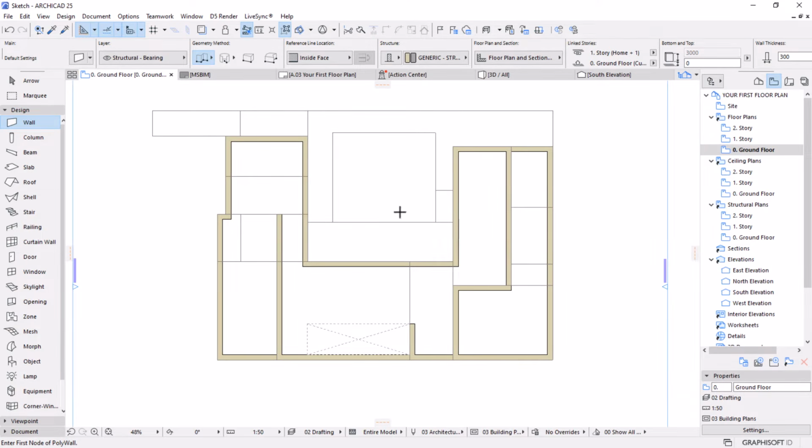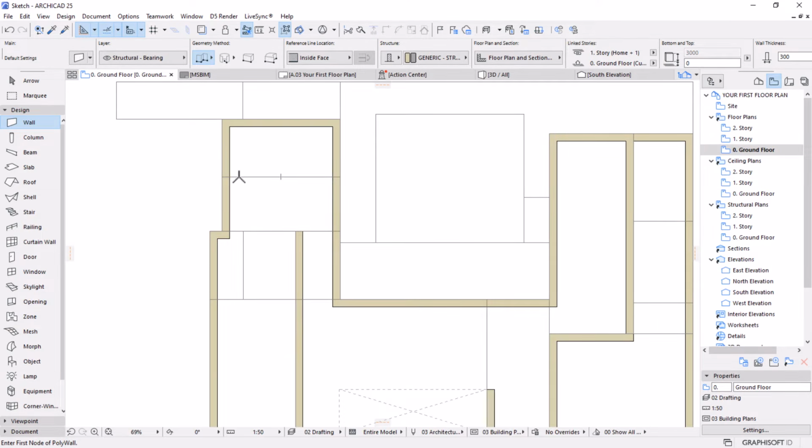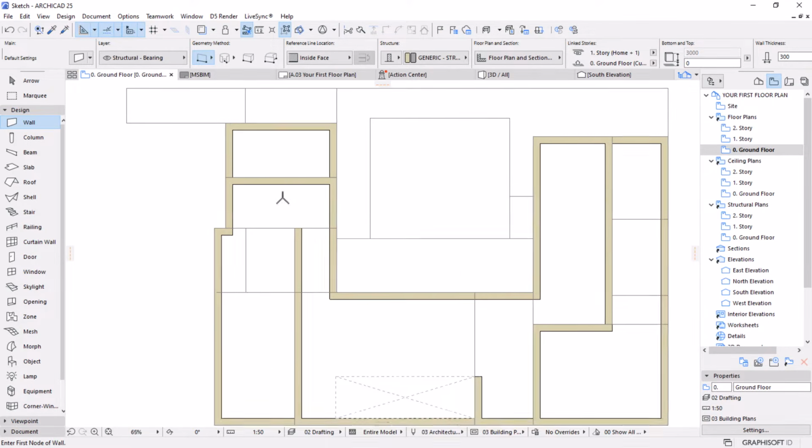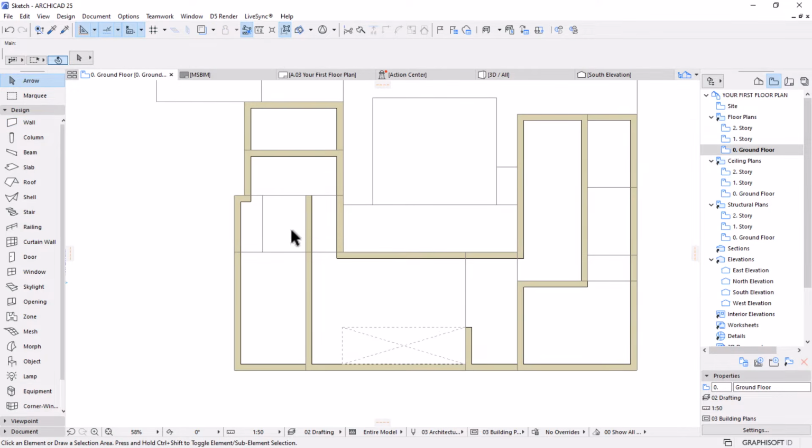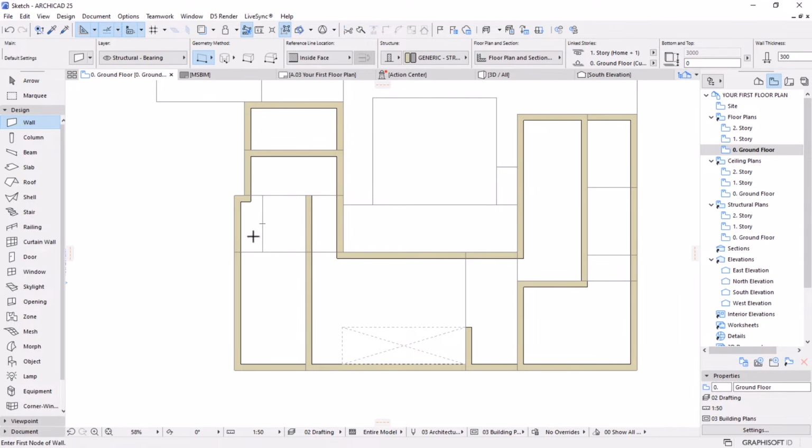We have another wall here, because now I'm drawing walls that are defined by 2 points. I need to change this to this method, so that I can just quickly draw it from here and then place it there. I'm not sure, should I keep? Yes, I think it's the perfect location. So I'll do the same to the other walls. Like we have another wall here, I'll press W to repeat the previous command, and then draw it to there.